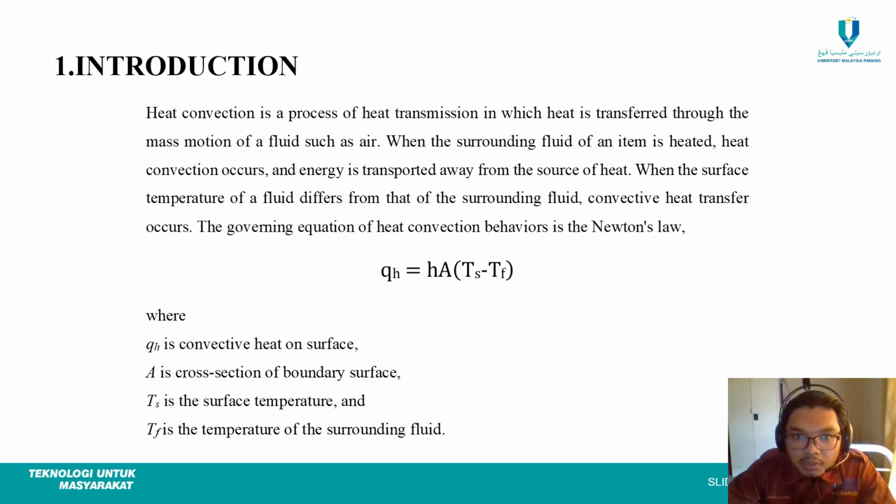The governing equation of heat convection behavior is Newton's law, which is Qh = hA(Ts - Tf), where Qh is the convection heat of the surface, A is the cross-section of the boundary surface, Ts is the surface temperature, and Tf is the temperature of the surrounding fluid.